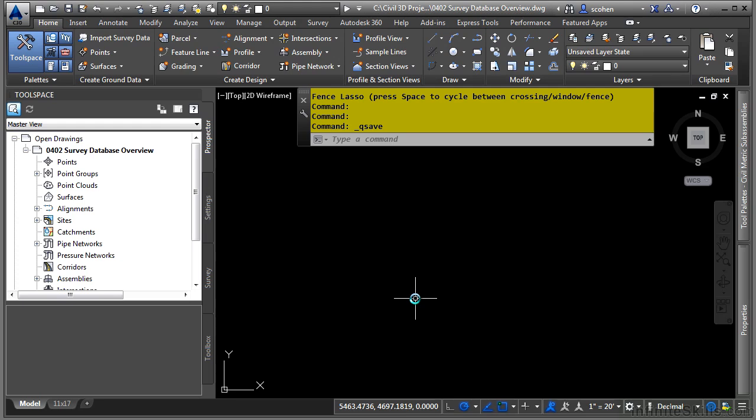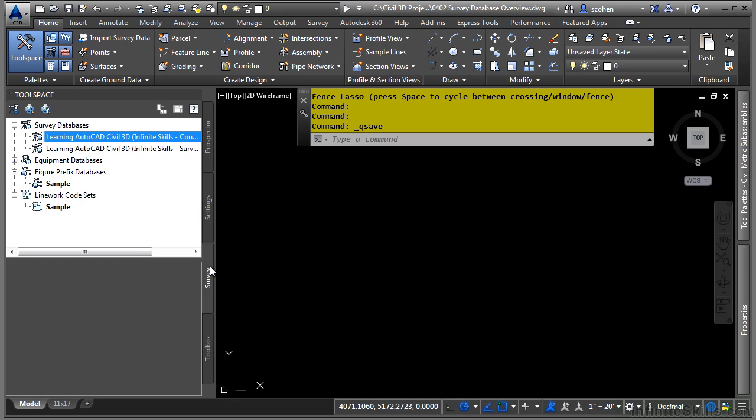In this video, we will discuss an overview of the survey database functionality. If you'd like to follow along with this video, please open the file surveydatabaseoverview.dwg located in the training folder as discussed in the Working with this Dataset video. The survey database contains all survey-related data and is managed in the Survey tab of the Civil 3D toolspace.